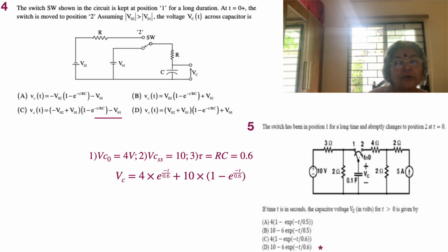passes through that inconsequential or irrelevant 2 ohms, so you remove the 2 ohms, and you see that now 5 amps is in parallel with 2 ohms. If you can accept this, it will enable you to do the problems in a very quick manner. So remove the 2 ohms in series with the source, but retain the 2 ohms in parallel with it. So you see that it's now the same as a 10 volt source, 5 into 2, 10 volt